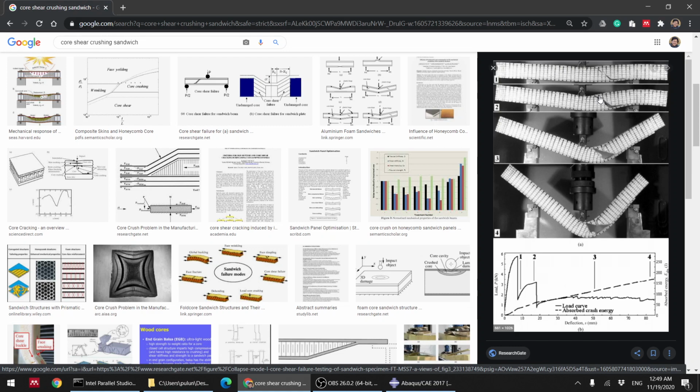But I just checked extended finite element in Abaqus on YouTube, and most of the tutorials have this crack location, the initiation site. So you need to tell it this is the initial crack, and then XFEM will take care of it and extend it. But that's not something that we want, because if you need to have an initial crack, then you have the same limitation as cohesive elements: you need to put it there from the beginning, right?